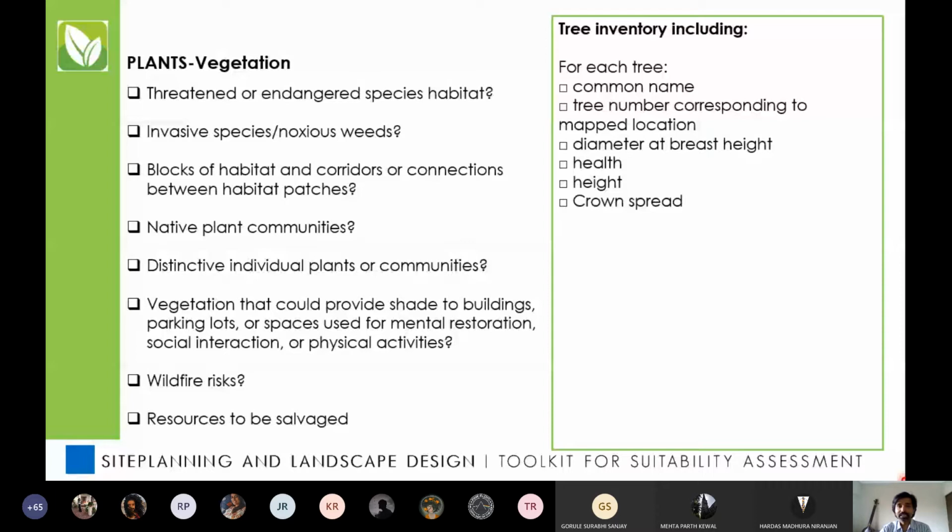And at the end of it, when your building actually gets constructed, you realize that all the branches of that beautiful mango tree have to be chopped because your architectural expression, or your building, has been so close to the tree. So when finally the client comes in on the day of the inauguration and looks up at the mango courtyard, he'll see only one stub that goes up because the branches have all had to be chopped. The architect thought maybe the tree had an equal spread, but the truth was that the mango tree grew to one side. So it's too late to control the damage. So it's important to understand the crown spread as well.